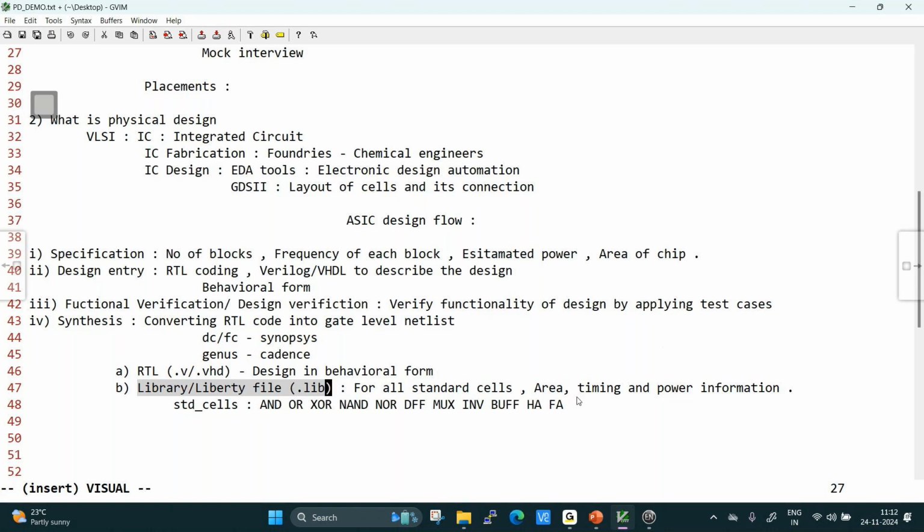So the last file, the third file that we use, is the SDC file, .sdc, Synopsys design constraints file. This file has constraints such as, after synthesis, what frequency of clock your design should work with. You have many Synopsys constraint commands, but for the time being, understand that you have the clock period. What clock are you using for this design? What is the clock period?